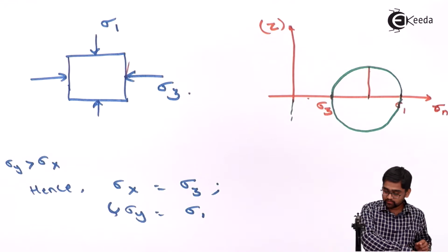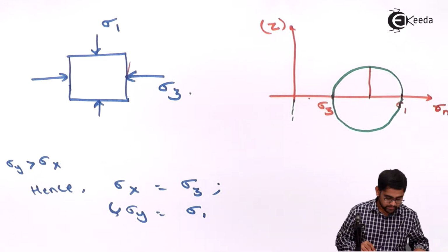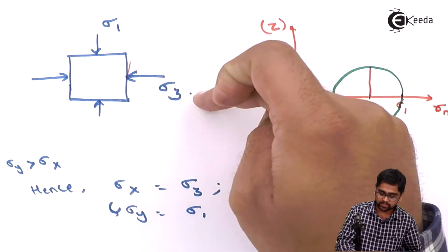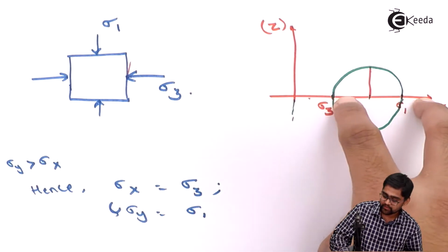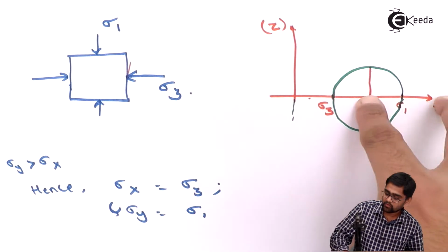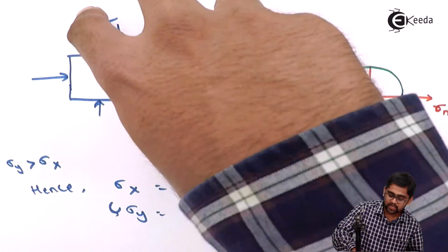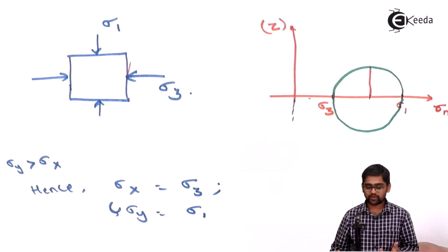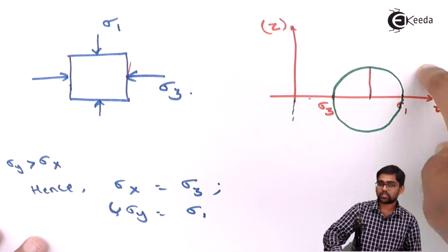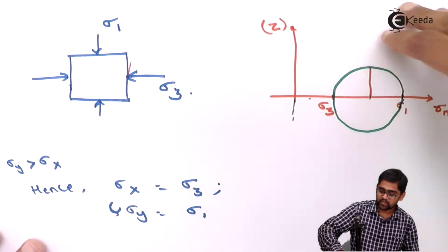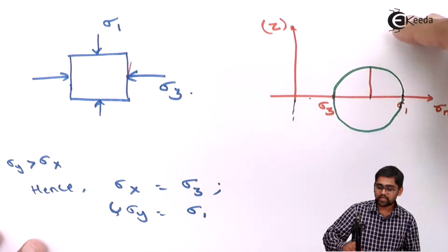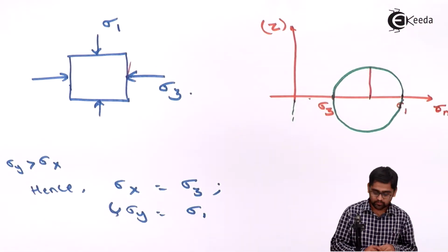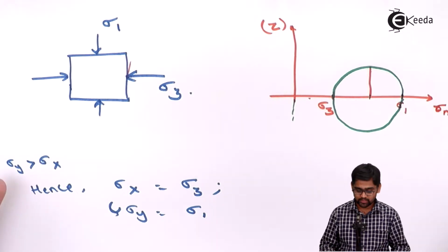Now the point of the discussion here is, this is the Mohr circle corresponding to one value of sigma 3 and sigma 1. So obviously if your sigma 3 goes on increasing, what will be the value of sigma 1? And whether in terms of the total stress or in terms of the effective stress, how will be the Mohr circle, and how will be the failure envelope, and how to determine that envelope. Again, that is a concept that needs to be discussed over here.